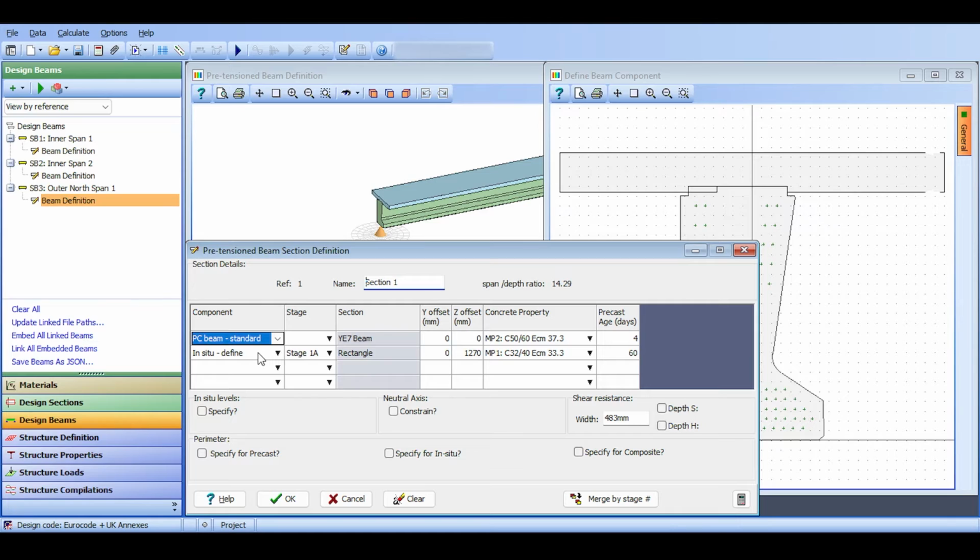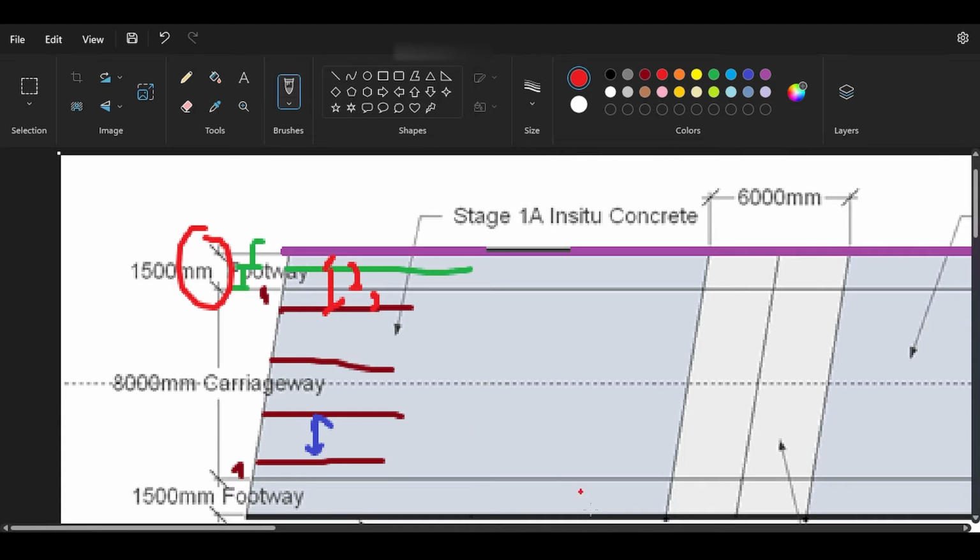No, this is changing. This here should be changed because, look, this is the centroid. It's not 1 meter on each side. At the moment, it's 1 meter and 1 meter on each side of the centroid. No, we said I want 1 meter on one side and 500 millimeters on the other side. Meaning that my slab is 1.5 meters because that's what you see here, 1.5, right? So I need to change that.